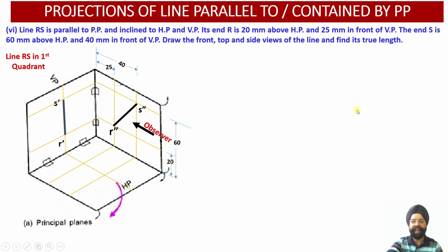But while I draw it onto the projections, I will be showing it onto this particular line itself. I have drawn it over here, assuming that I want to show you these projections uniquely other than the ones drawn on the x1 y1 line. This is my apparent length because this is the reduced length. Why? Because my line R double dash S double dash happens to be inclined to the vertical plane.